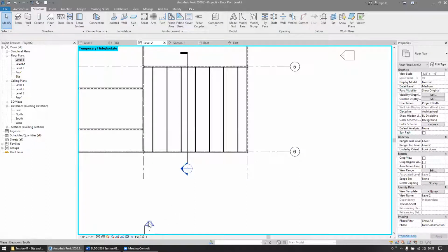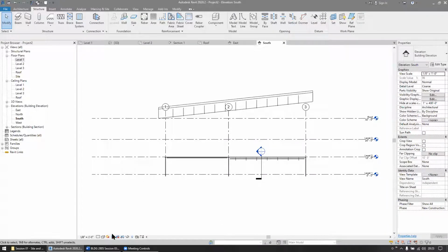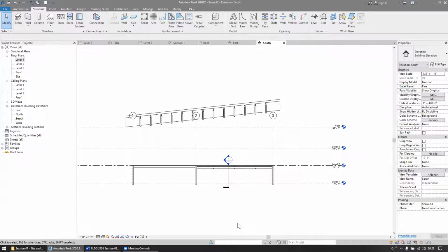So this is similar to when we put on an extruded roof. Now, if I want to draw a beam here in this view, and I want to draw it in elevation, I need to tell Revit which working plane, front to back, like depth-wise within this elevation view, that I want the beam to sit at.